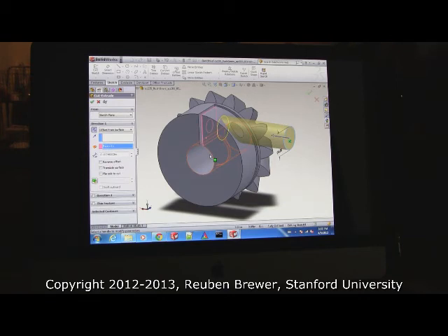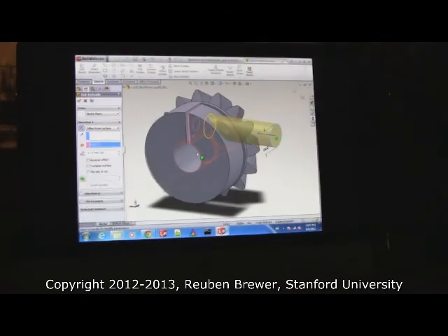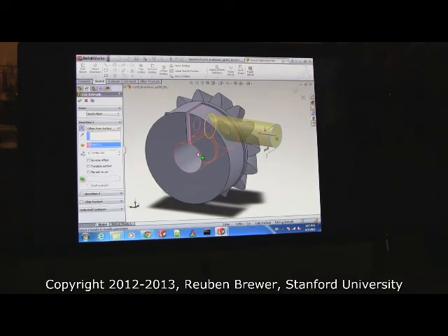Okay, does everybody have an extruded circle? 6.5 millimeters is the diameter, divided by 25.4. What was the amount that we cut off when we did the cut extrude to make the whole part stubbier? We made it so that the width was 8 millimeters. If you want, for now just make the diameter a little smaller so it fits, and then you can go back and fix it later. It was 8 millimeters from the inside surface, not the outside. That's the difference for you.